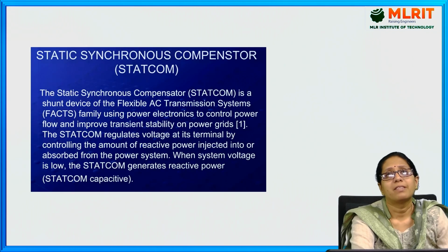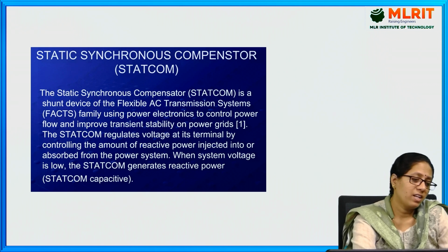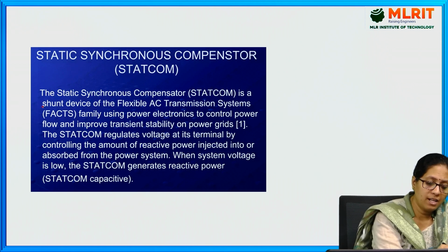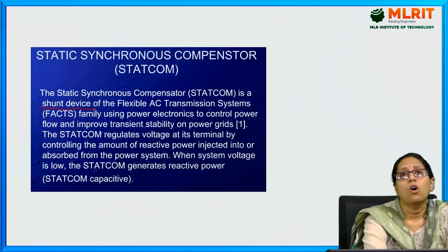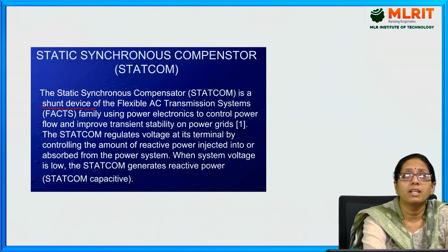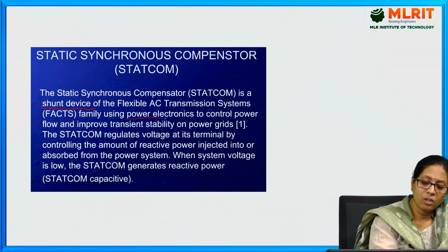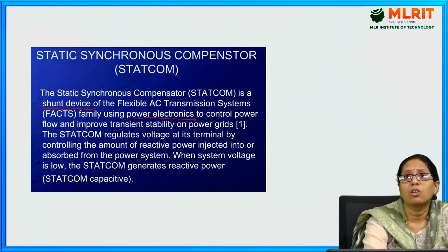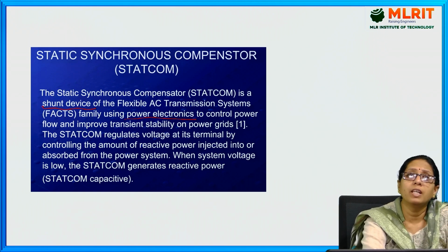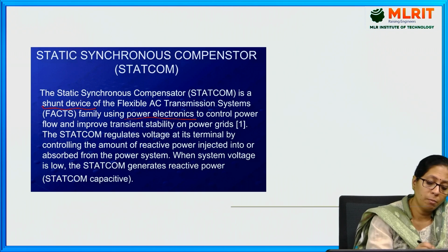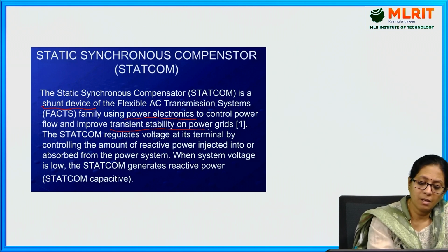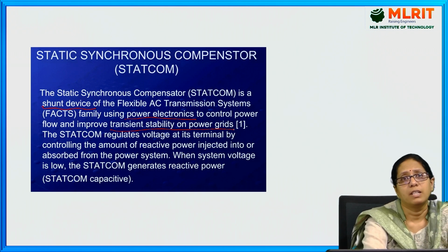Next type is STATCOM, that is static synchronous compensator. The STATCOM is a shunt device. Shunt, as I said, means parallel. It is a shunt device of the FACTS system, that is flexible AC transmission system, using power electronics for control purposes and in order to improve the transient stability of the power grids.